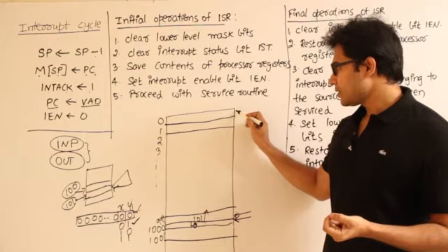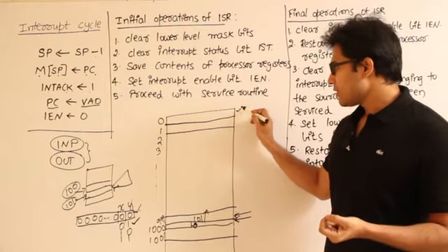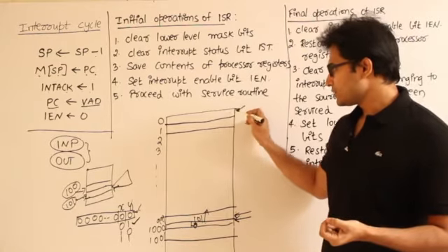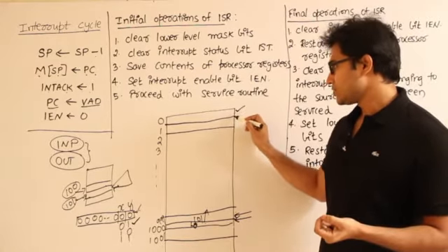So if the interrupt service routine of the hard disk is going to start, it is impossible to start the next program here, the ISR of the printer. Therefore we are not actually going to put the ISRs at this location. What we'll put here is the address at which that ISR is present, right?